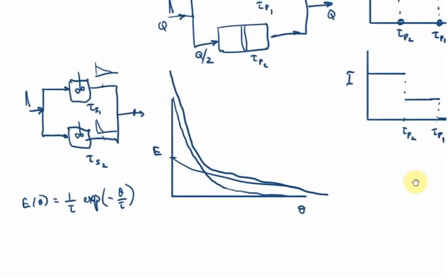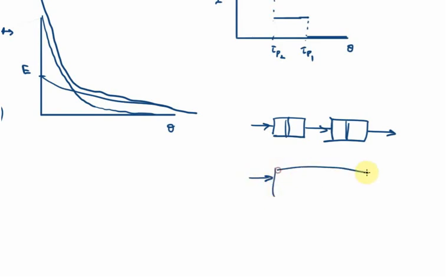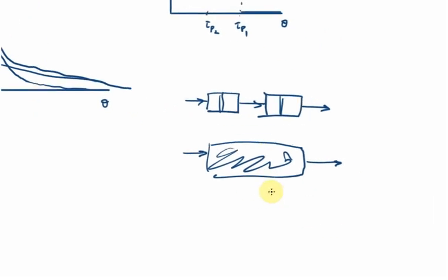Another one to think about is in series, right? So let's look at a PFR in series with another PFR. And again, this is a model of some real reactor. So we've got some real reactor here, and its mixing pattern might be such that this is a decent representation. So sketch out for yourselves the internal and exit RTDs. Maybe take a minute and try to estimate what your RTDs look like.